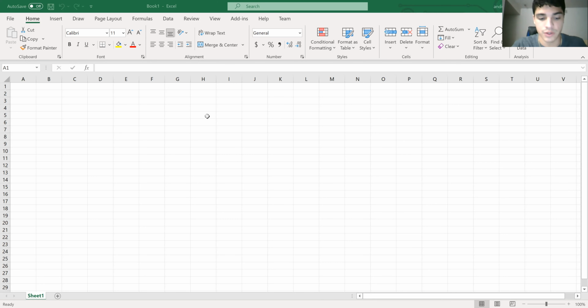And the next thing you want to do after that is get the minimum CD value. And now we just set that equal to min, and then highlight basically the C13 through C33 row. It's going to give us the minimum value as 0.063, which is going to happen at basically angle 0. So now we know that this happens at angle 0.